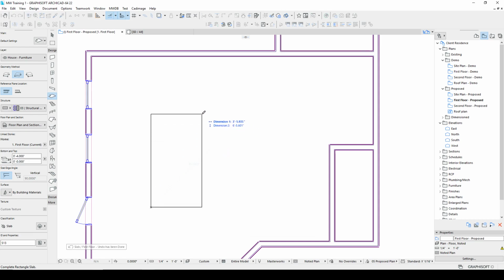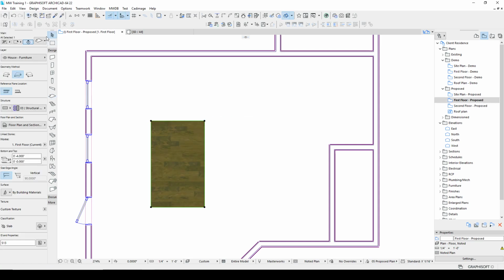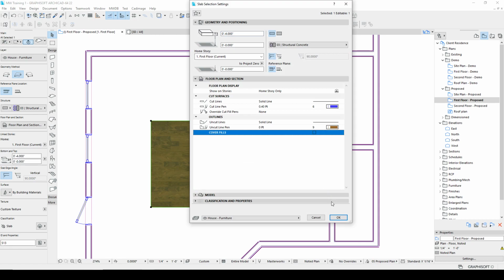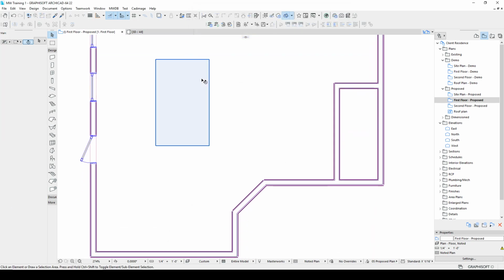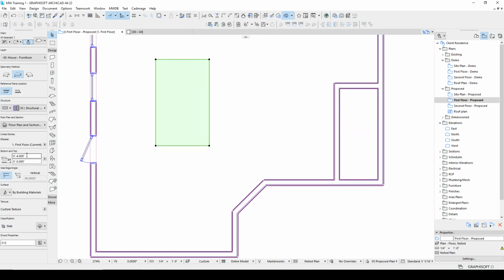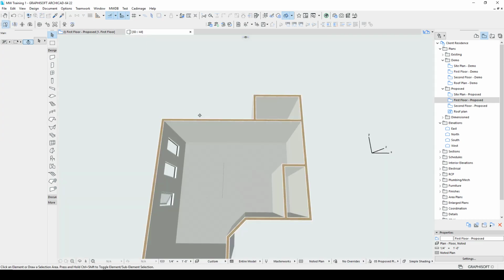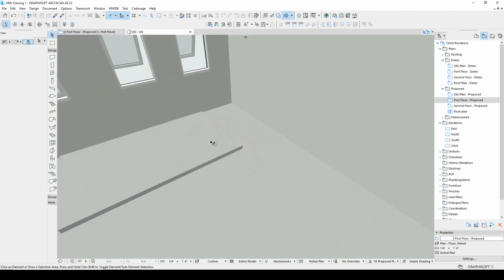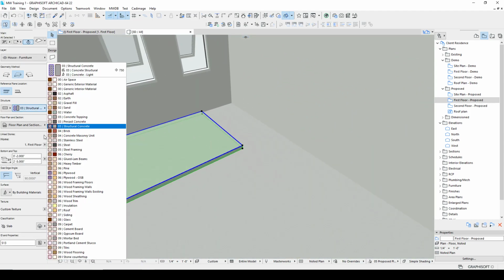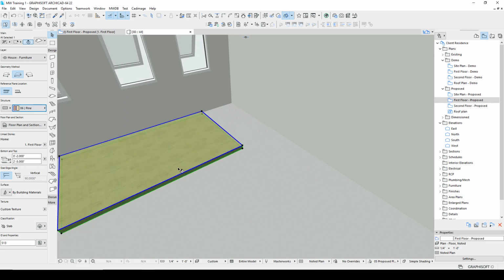Okay, so I'm just going to go, first dimension is 44 inches. Second dimension is 72 inches. There's a table. I'll go ahead and turn off the cover fill. And I'm going to set the tabletop to 2 inches. And I want this to be 29 inches from the top. Good. And I can either override the material. I'll just make this a pine top.